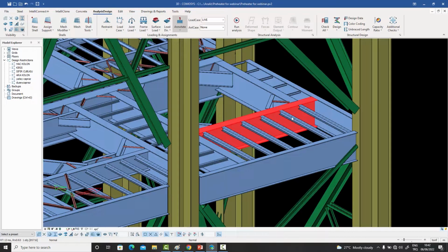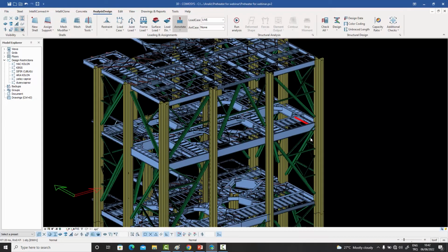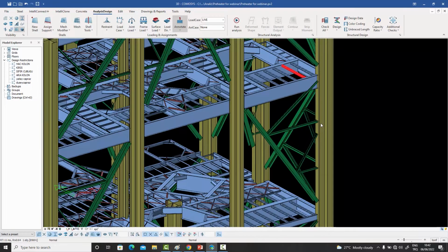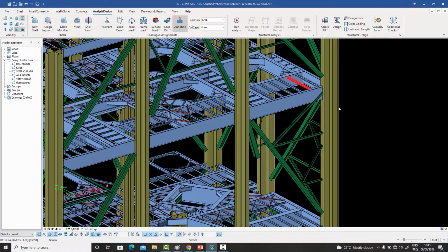And therefore, it will provide buckling support for them. Now, this obviously depends on, maybe this is not a good example, but if we had, for example, girts over here or roof purlins, you might or might not want to include them as providers of buckling support for the column. In industrial buildings, it's very common for the girts to be removed temporarily for maintenance purposes. So although they do exist, you might not want to consider them for your buckling support.